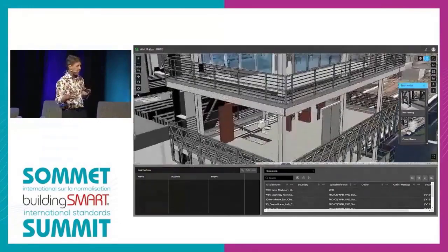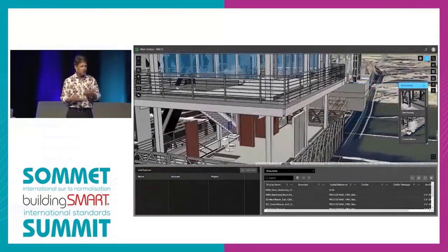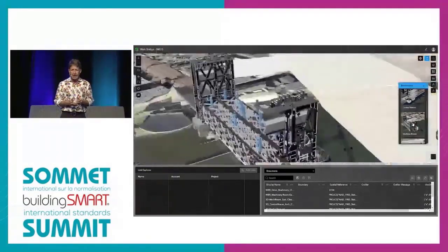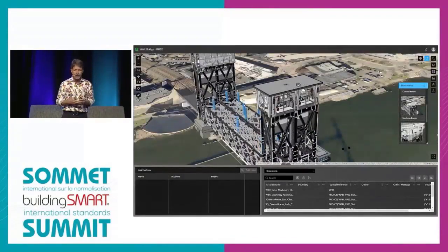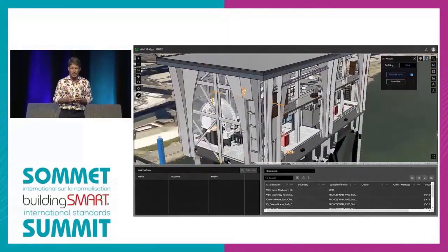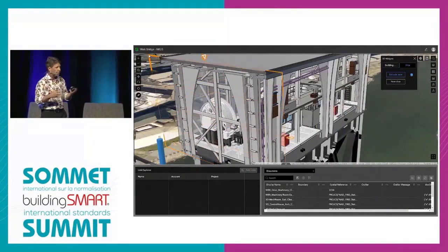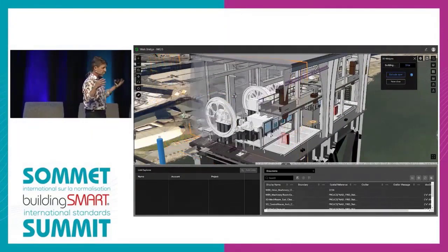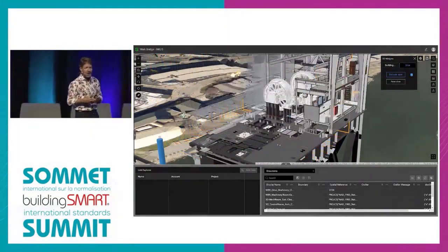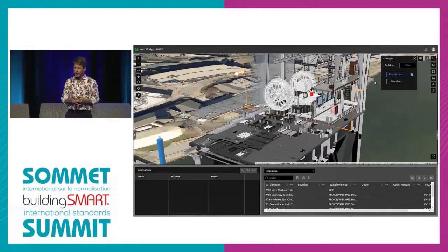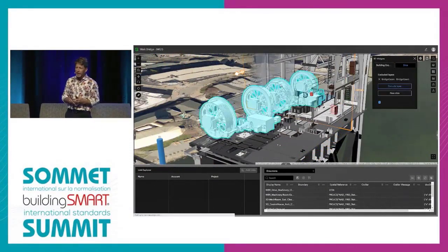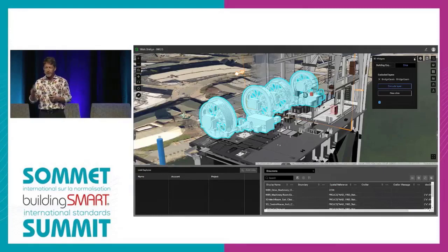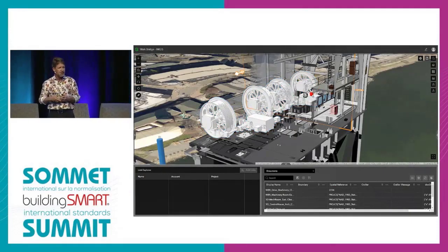This bridge is made up of, like I said, multiple BIM environments brought into GIS and then delivered out in this ArcGIS GeoBIM solution I mentioned earlier. So all the capabilities you'd expect of a CAD or a BIM-like viewer, the ability to slice and dice and understand context. Here slicing through the lift station above this 70-year-old bridge,